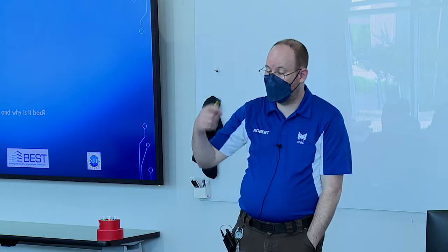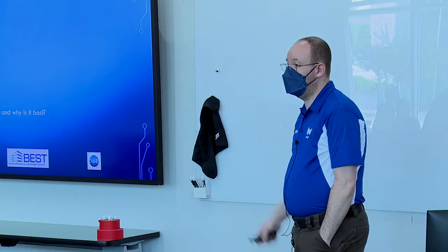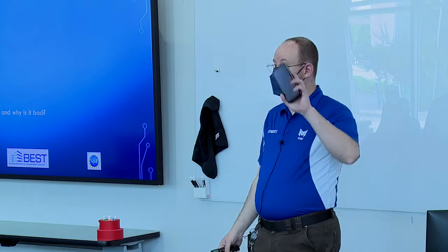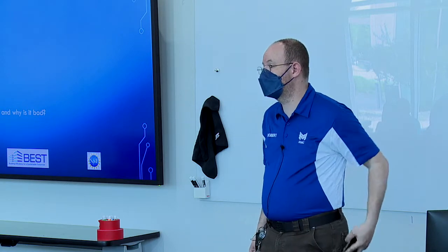we send messages. Email is one of the most useful ways or common ways that we send alarms. Okay? And when I say we send emails, I don't mean we just send emails, because email is one thing, sure. But we can also email to text. So you can text your on-call phone saying that this thing is in alarm.